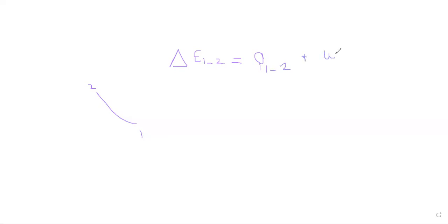Now, in general, when we do a theoretical model for engines, we model the processes of compression and expansion as adiabatic processes. Whenever we say it's an adiabatic process, you can say that Q is 0. So we can consider that during compression, we only have work getting in, and then delta E, the variation of energy from 1 to 2, is equal to Win.